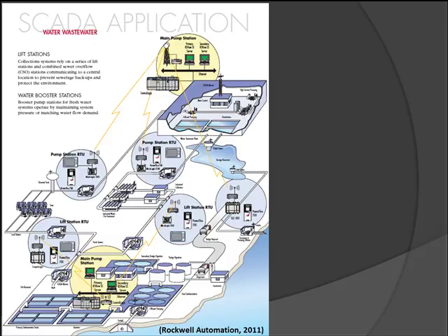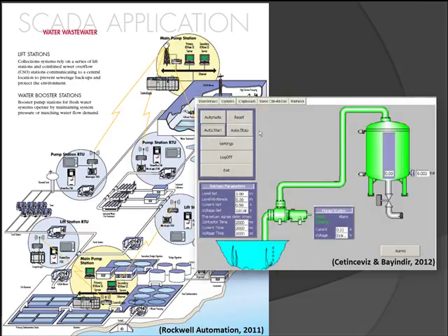This infographic illustrates the purpose of a SCADA software package when applied to a water treatment application. At the top of the infographic, we find the main pump station computer that allows plant operators to connect to multiple remote pumping stations distributed throughout a city to control automated equipment, monitor reservoir levels, and acknowledge alarms from a central computer using graphic screens similar to the one shown in this slide.